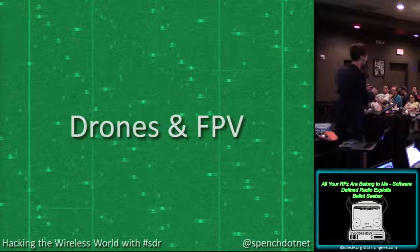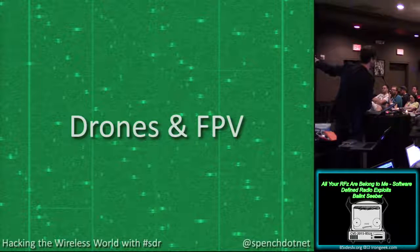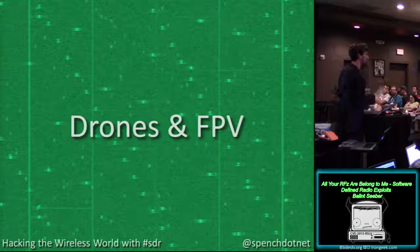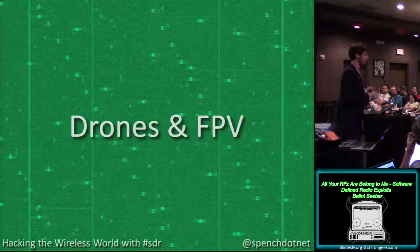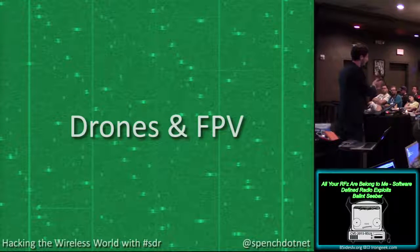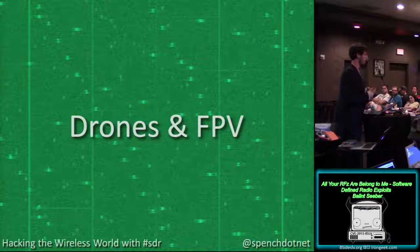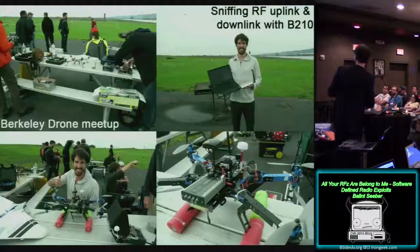And these remote controls use frequency hopping, so you can see that you end up having these little packets that aren't transmitted on the same frequency all the time, but they hop through the spectrum. And this allows for lots of people to be using this same band at the same time. So it means that you don't have to individually allocate a particular frequency to a person. They can all hop through this region, and if all goes to plan, they won't interfere with one another. So it's a really effective way of sharing the radio spectrum between multiple users. So I went out there and used a B210 to capture that radio spectrum.